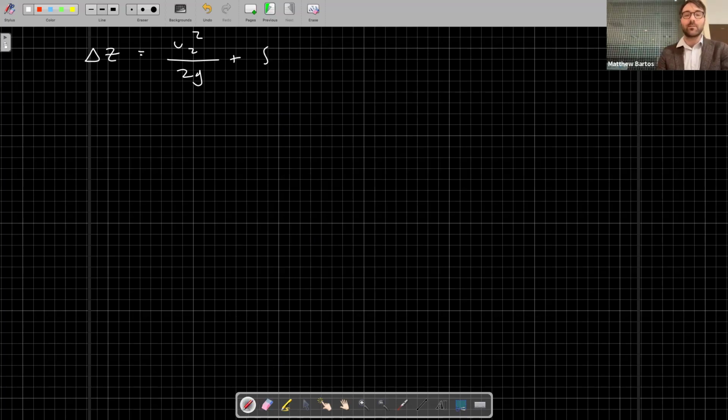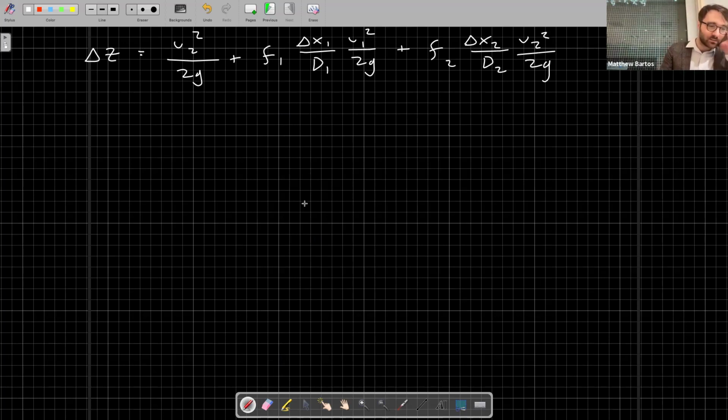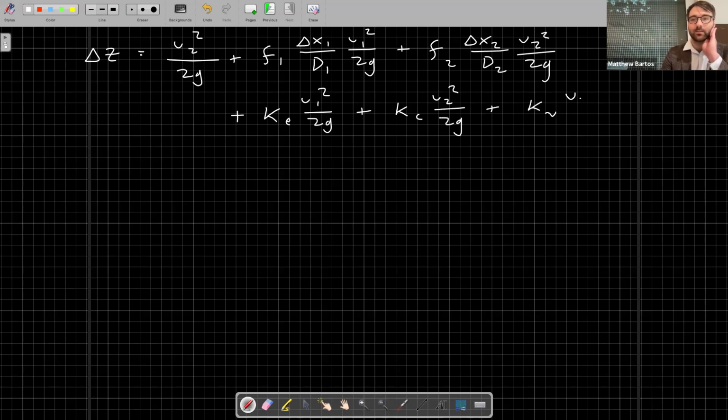For the major losses, we have F1 times delta X1 divided by D1 times U1 squared over 2G plus F2 times delta X2 divided by D2 times U2 squared divided by 2G. So those are our major losses. To that, we need to add our minor losses. That's going to be plus KE for the entrance loss times U1 squared over 2G plus KC times U2 squared over 2G plus KV times U2 squared over 2G.